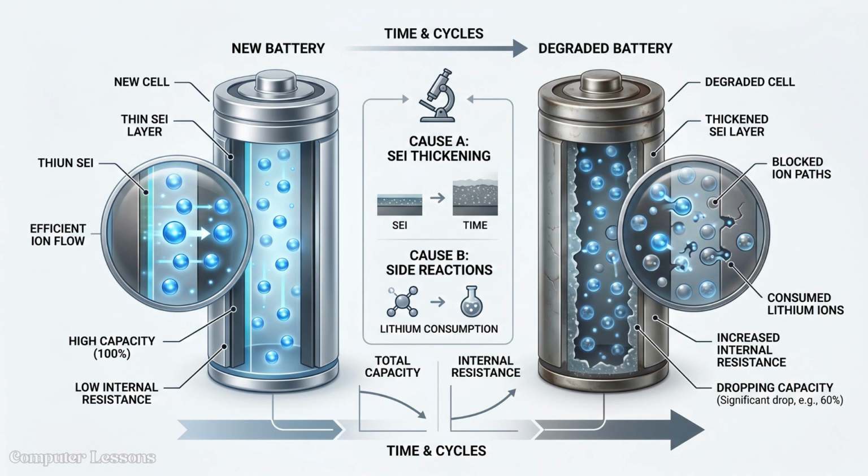But every battery has a limited lifespan, degrading slowly with every single charge and discharge cycle that it completes. This degradation is caused by side reactions that consume the available lithium or thicken the internal SEI layer. Over time, the internal resistance increases and the total capacity to hold a charge drops significantly.